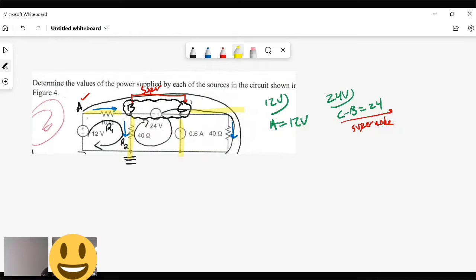So that way I go, okay, if that line's touching it, then that source has to be working. If this line's touching it, then that has to be the current that it goes with. Does that make some sense? So that's how I like to think of it. And that way I don't miss it, because it's very easy to miss a line on the supernode. And if you miss a line, you're going to mess it up.